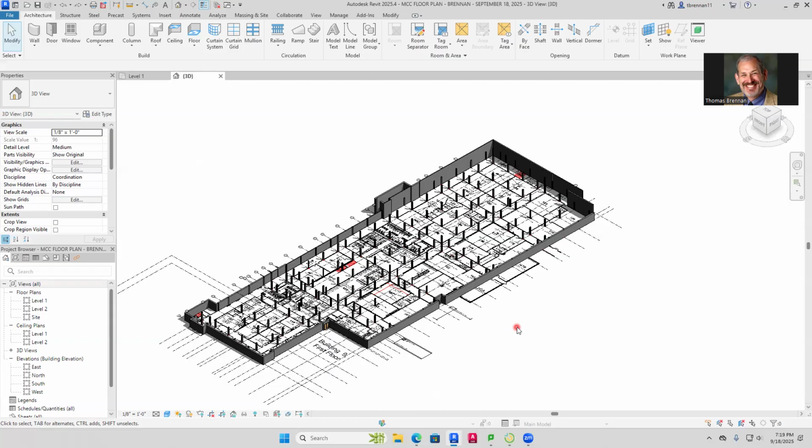Because I don't want to go and pick all the walls individually. And we have a lot of wall types. We have 8.5-inch walls, 16-inch walls, 1-foot-4-inch walls. There's a lot of different walls, but they're all walls. That means they're all the same category. That means there is a way to select all of them and isolate them so we can do surgery on them all at once.